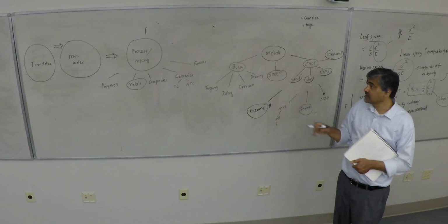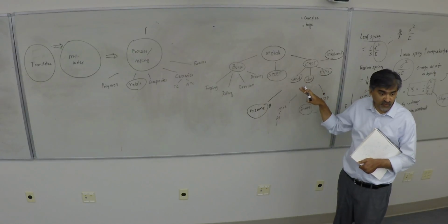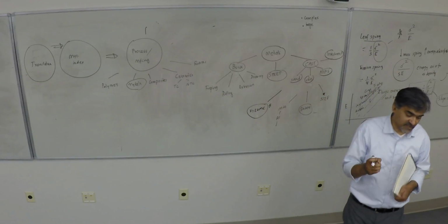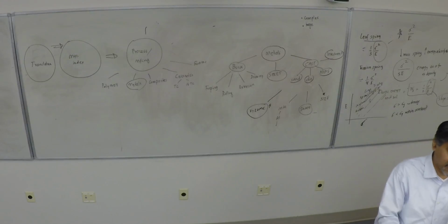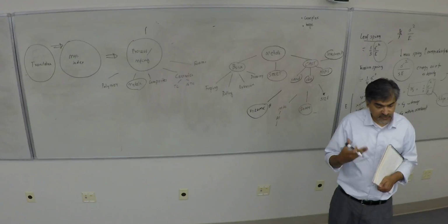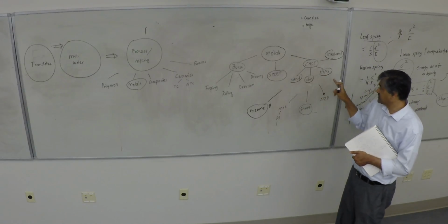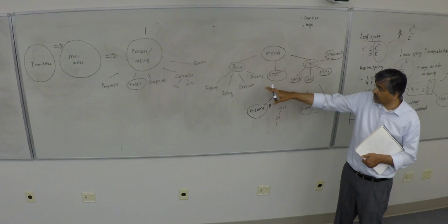Therefore, there's a lot of flow modeling work done, in the sense of this viscous flow, to make sure that the right entry points in the die are managed, so the material will have very minimal splash and issues that can create voids in the part. So that is a very different type of problem than these.